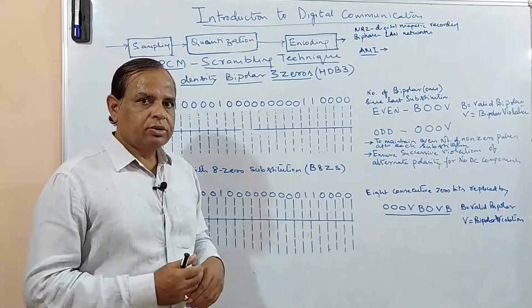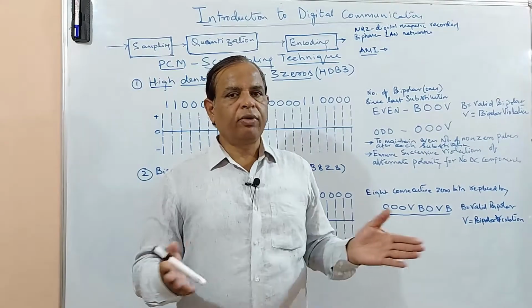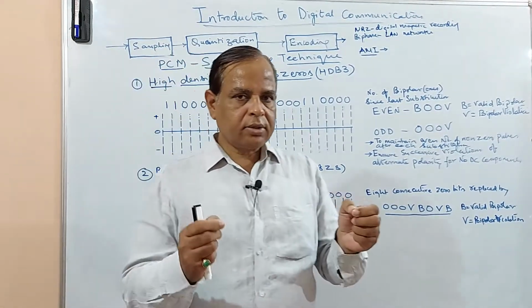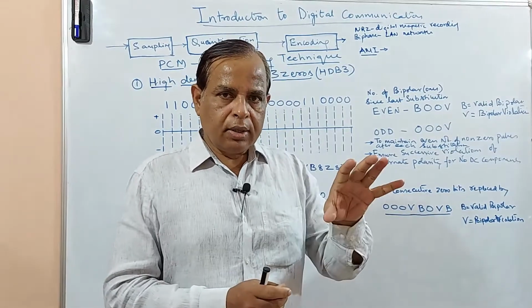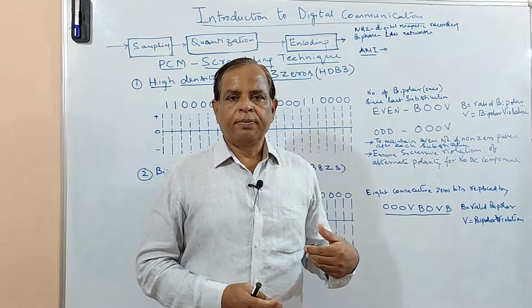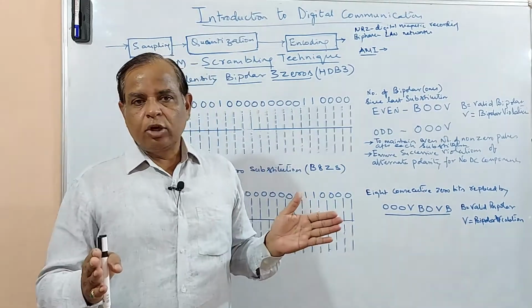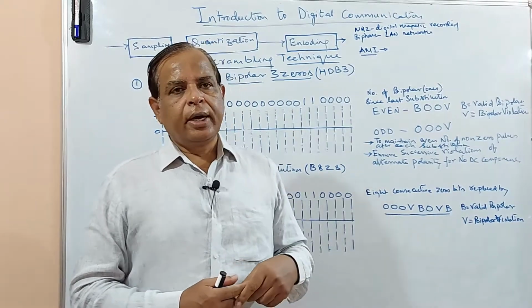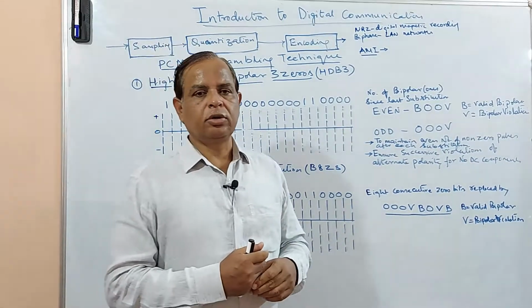But at the same time, we have seen other schemes called biphase Manchester and differential Manchester. They are extraordinary, all the things have been justified: synchronization is excellent, there is no DC component as a lot of signal changes are there, and error detection capability is also there.